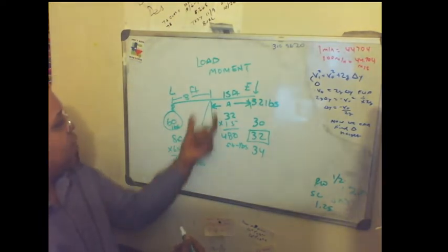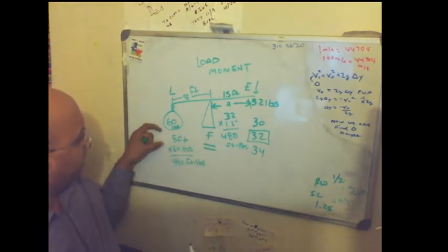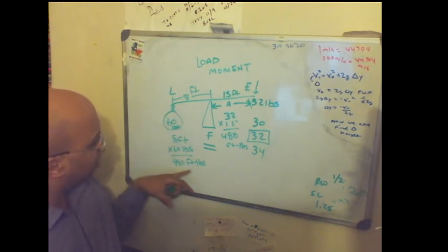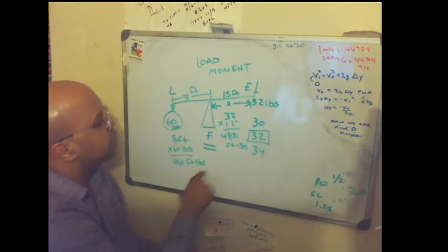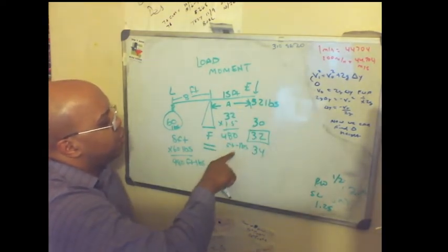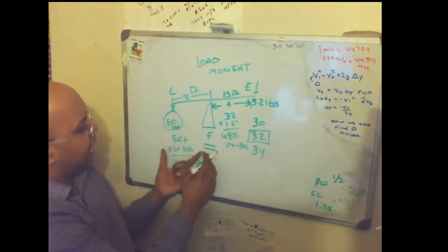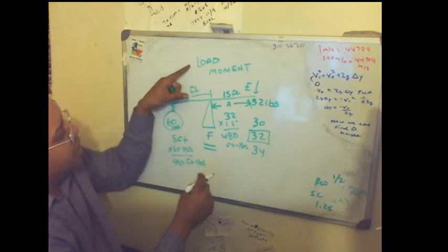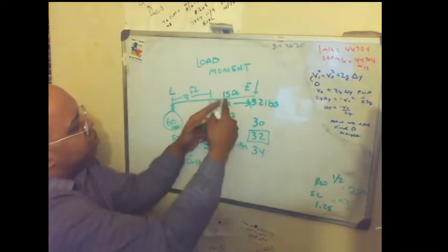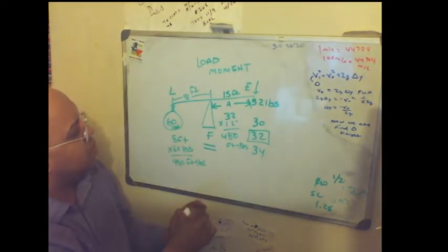So that's why the fulcrum is the equal sign. If we're going to have 8 feet and 60 pounds, we have produced a load moment of 480 foot-pounds. And then 32 times 15 is 480 foot-pounds. So the system balances out if we think of it as an equation. Load moment is a function of distance and weight, just like this load moment is a function of distance and 32 pounds of weight. All right?